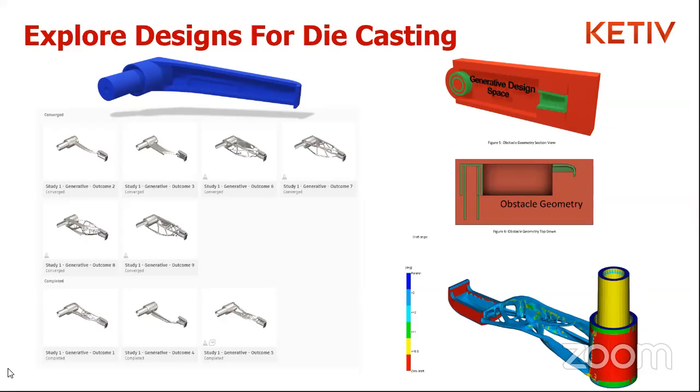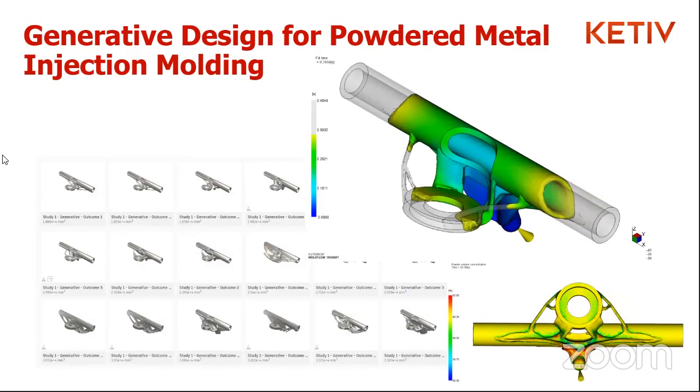So it's what I've termed man versus machine. It's all these things we need to know to make good decisions for plastic components. We've opened up artificial intelligence with generative design, applying it to solve a problem: giving the computer some areas that we want to preserve, a space we want to live in, and obstacles that we need to avoid, and then allowing the software to run not just an FEA analysis, but also shape generation based on the process type.